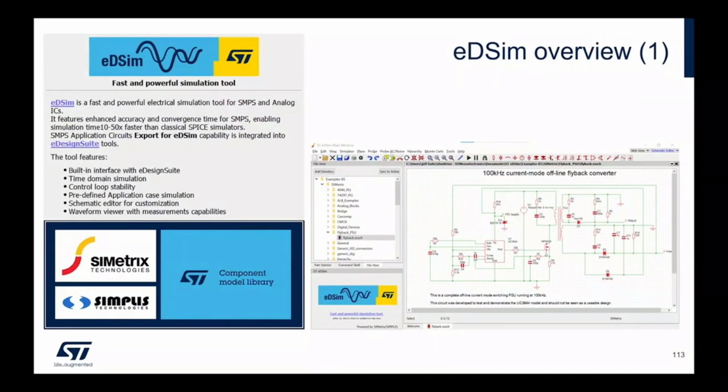In this case, we're going to be simulating a buck regulator, our new DCP3601, which is a 36 volt, 1 amp synchronous buck for industrial applications. And what is great about EDSim compared to PSpice is that EDSim was specifically designed to simulate very fast and quick switching mode power supplies.